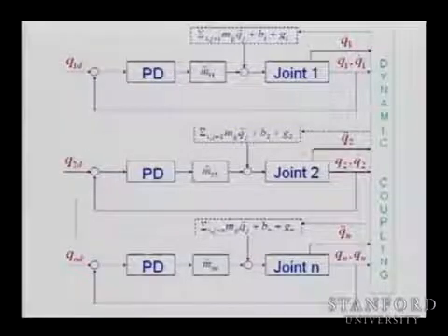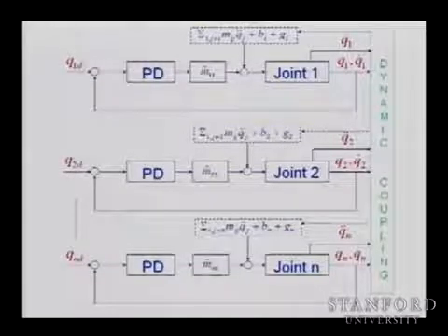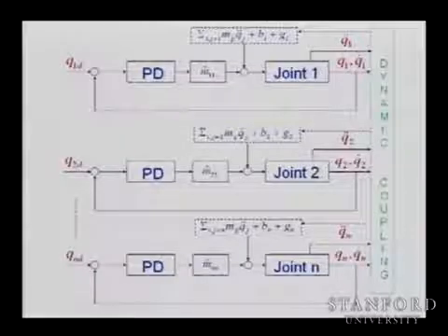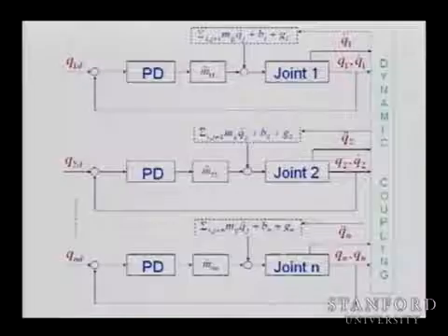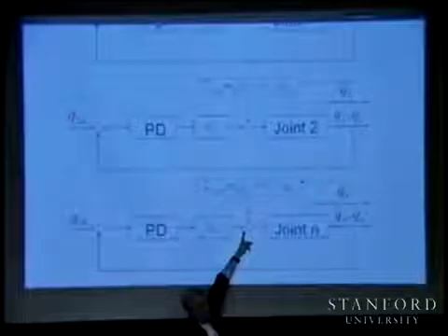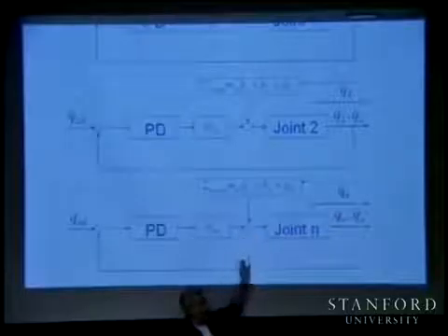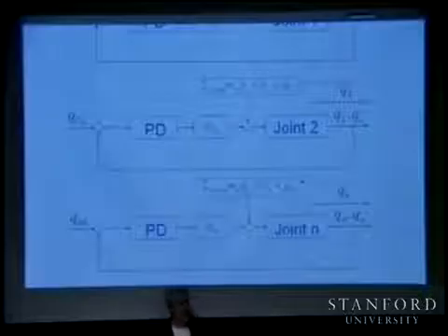Well, I mean, the idea is right. Basically, let's use this model. If we know the dynamics in advance, we can use this model. And essentially, what do we need to do? We need somehow to counter this force. So how do we counter this force? We compute it and inject it back into the system to counter it.